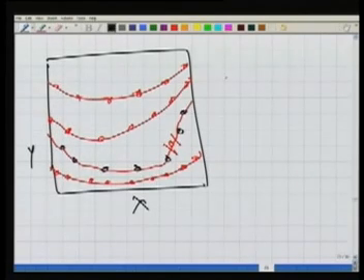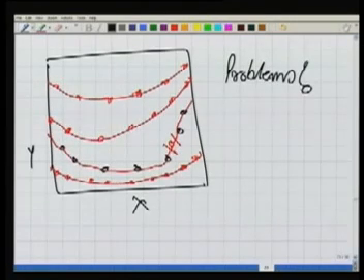Well, are there any problems? Right now we are doing it on our screen, and doing it on a screen with a pen is very easy, but actually doing this in the field is difficult. This trial and error, I want to bisect 1 meter. The cross wire of my level should bisect 1 meter.